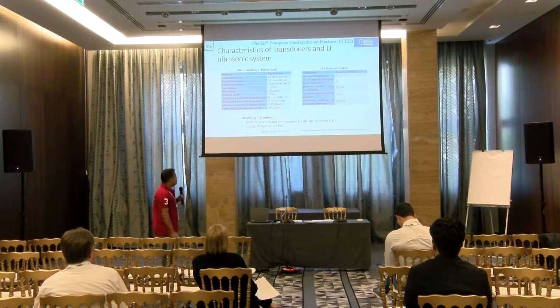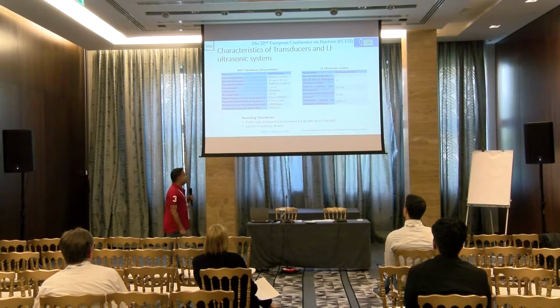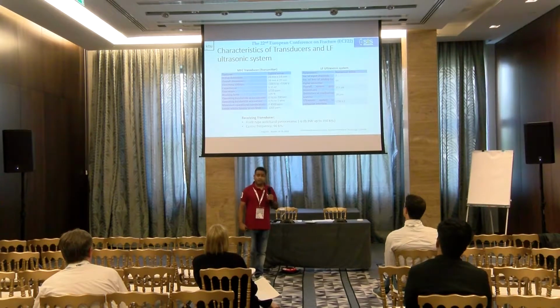The receiving transducer is a point-type wideband piezoceramic transducer, whose bandwidth is -6 dB up to 350 kilohertz, with a center frequency of 90 kilohertz. The parameters of the low frequency system are mentioned here. The low frequency ultrasonic system, receiving transducer and all other components apart from the MFC transducer were developed by the Ultrasound Institute, Kaunas University of Technology.